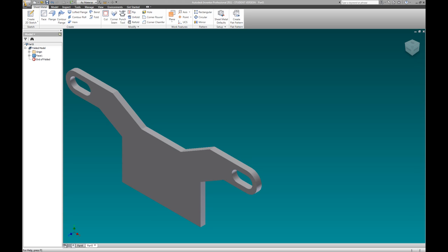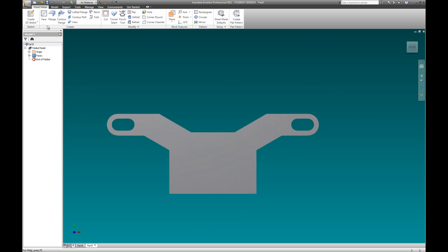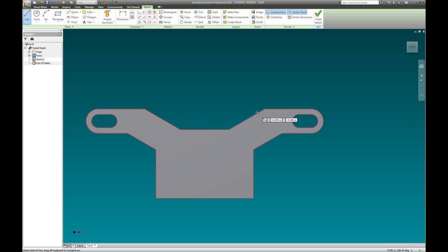As I showed you in the first little video, we're going to create a fold line. So I'm going to come across here and go New Sketch. I'm going to pick this face here. I'm going to use a construction line just because it doesn't leave a line later on. And it's important that you pick the edge. You can't just draw a line from one side. You can't do this. It won't work. You actually have to define the edges of the piece with your line.